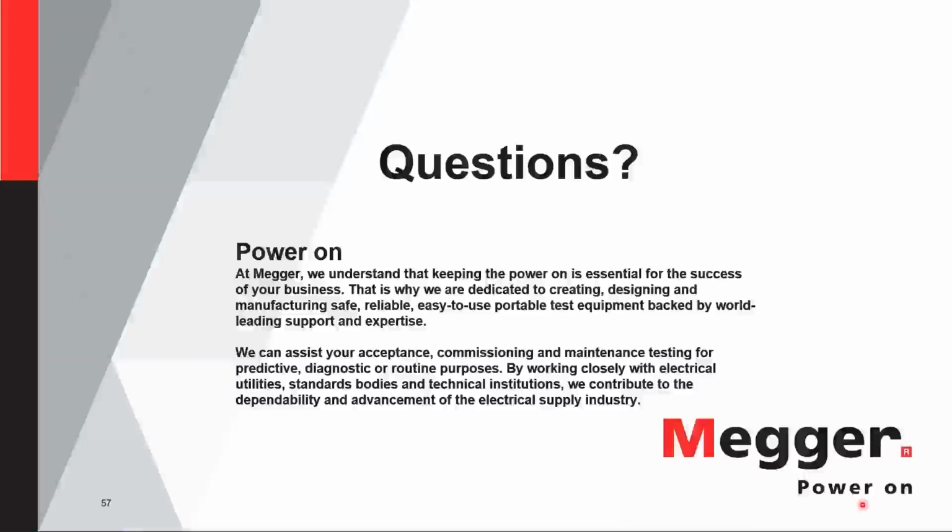Like I said, you can do that in the field by means of a voltage checker accessory, and I would recommend doing that at least once or twice a year. And if the calibration needs to be adjusted, that needs to be done in a calibration center. The recommendation for that is to do it once a year.